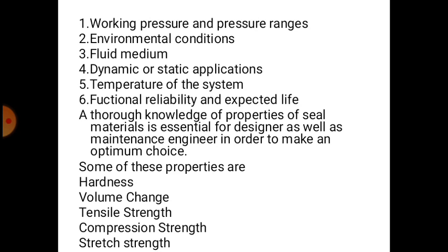So how to select the seals? They are selected according to the working pressure and pressure ranges. Some applications require high pressure and some applications require low pressure, so according to the pressures we are going to select the seals. Environmental conditions: according to environmental conditions we are going to select the seals. According to the fluid medium, whether dynamic or static applications, temperature of the system, functional reliability and expected life.